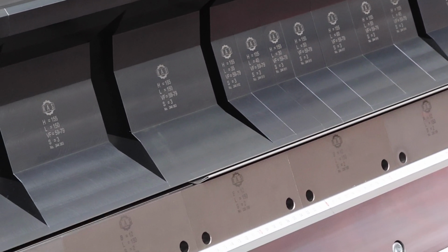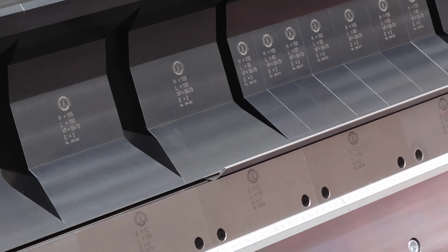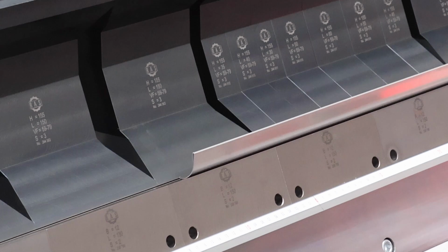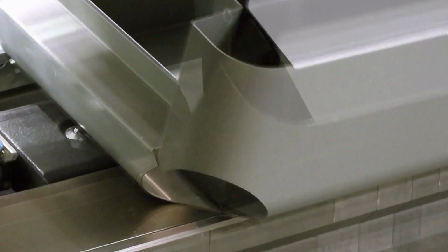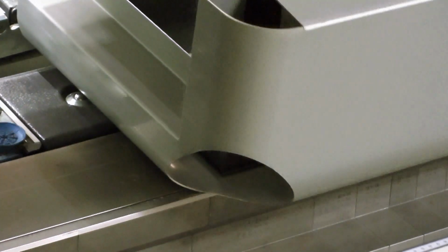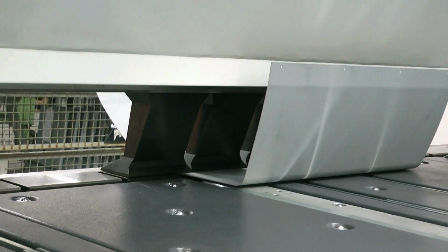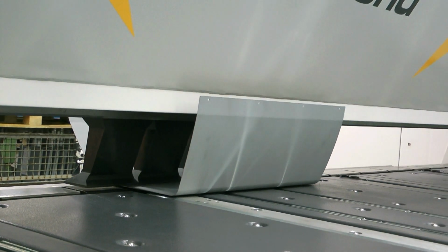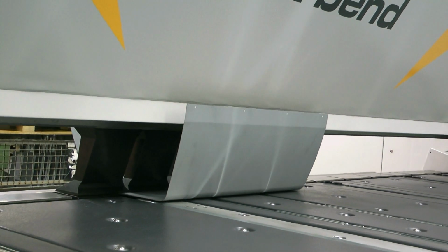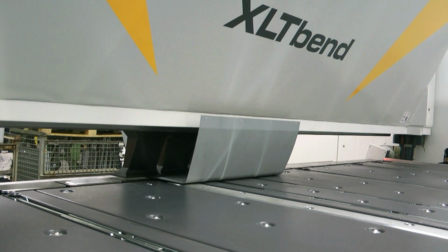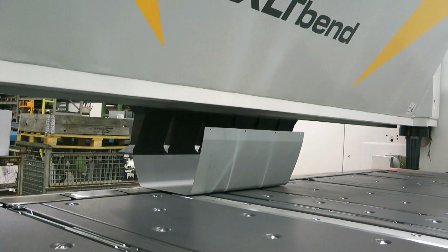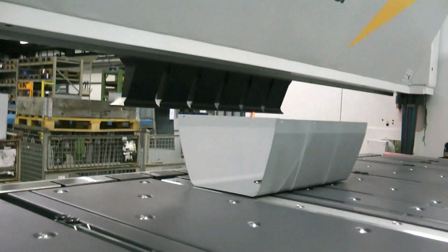For thin sheets, the folding beam remains at its programmed angle, and the upper beam forms each bend during its closing motion. For thicker metal, the folding beam swings to the required angle for each bending step. When step bending, automatic positioning using suction or a manipulator is especially advantageous. The automatic advancement of the sheet accelerates the bending sequence, avoids manual reposition errors, and even allows large and small radii to be bent in the same sequence without interruption.